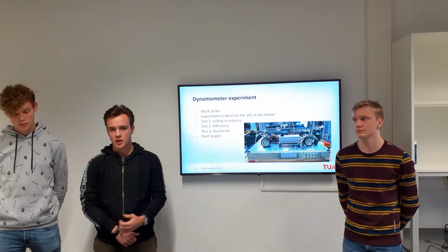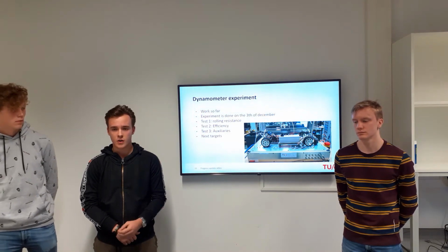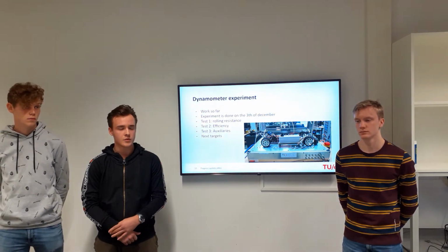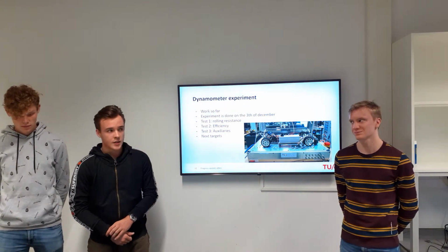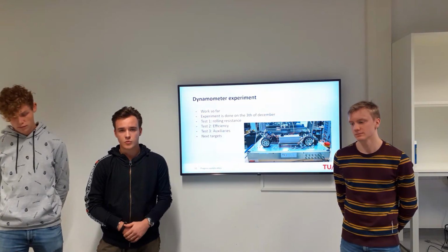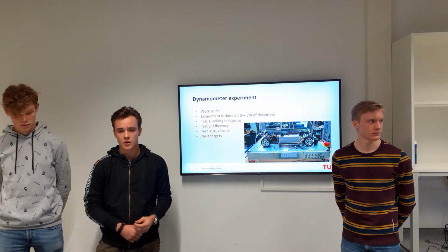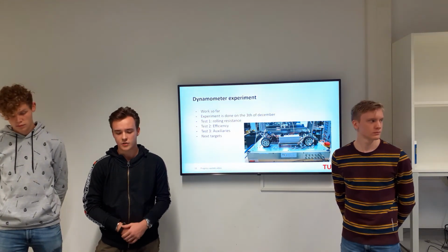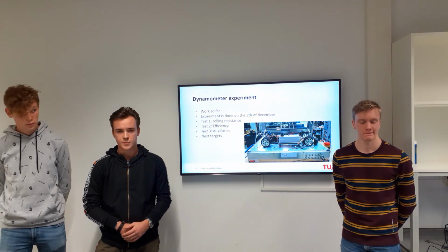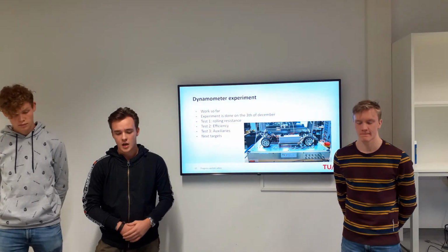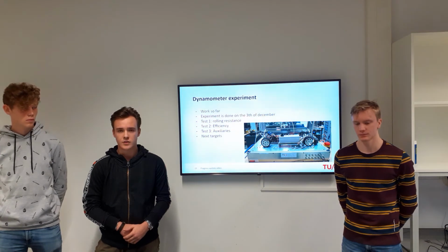auxiliaries. The auxiliaries are a kind of accessories which consume power but don't provide to the drivetrain of the car. In this test, the car will not be moving, the motor will not be producing any power, so the only thing consuming power from the battery will be the auxiliaries. So after this, we'll be doing the experiments on the 3rd of December. And after the experiment, we will need to work out the results from this test.